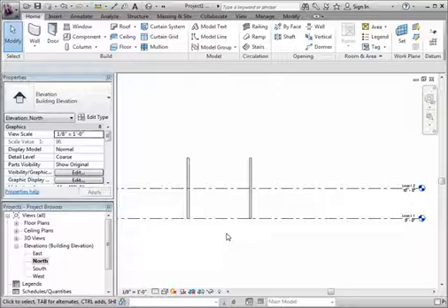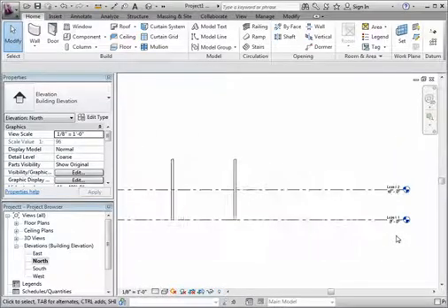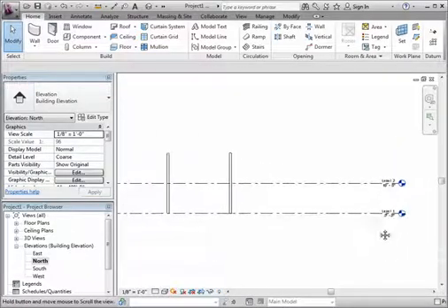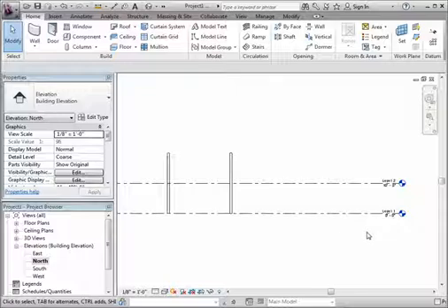So when you open up a new Revit file, it loads a template, and it loads a bunch of content. So it gives you a bunch of, for example, wall types and door types and window types, and it also makes views for you. So for us, it made 4 elevation views, and it also made 2 levels for us. So it made level 1 and level 2. Presumably, you guys understand what these levels actually mean. They indicate the different floor levels in a building. We're going to put a floor on level 1, and we're going to put a floor on level 2 a little bit later.